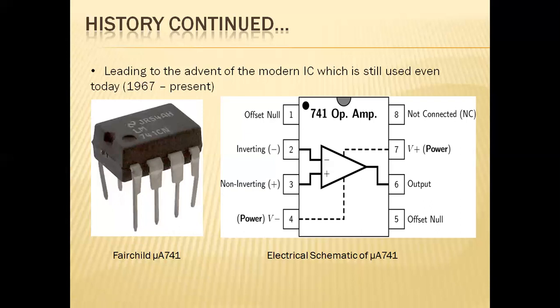If there are any additional parameters other than the ground connections, those need to be kept in an idle mode, without passing any power supply into that component. That will be connected to this NC port, which is the not connected port, pin 8. So the major criteria are the inverting and non-inverting inputs, and the output that is obtained based on the given input to the operational amplifier.